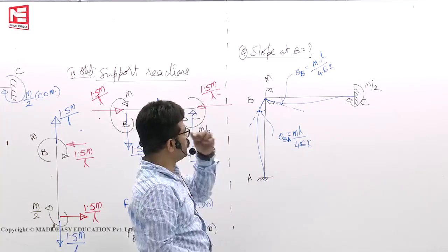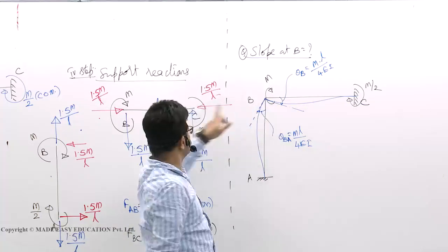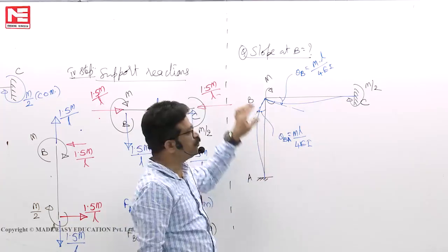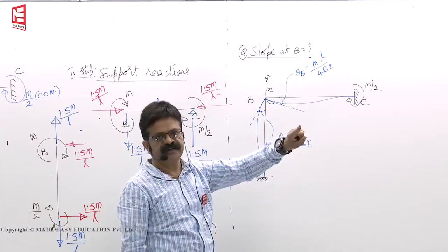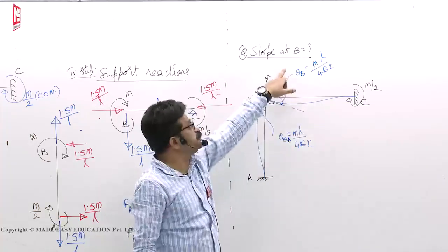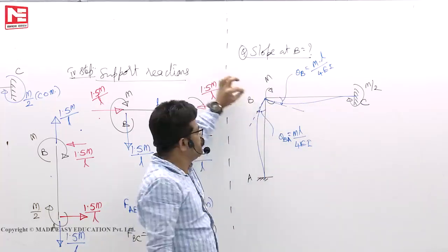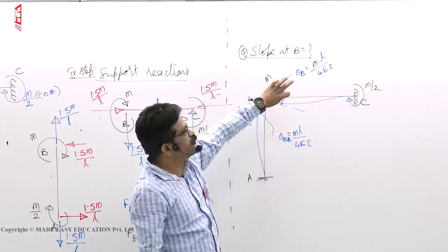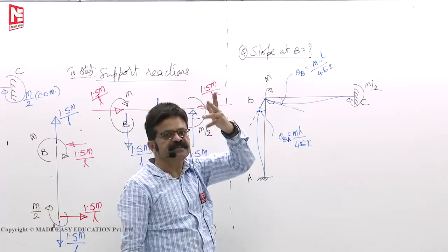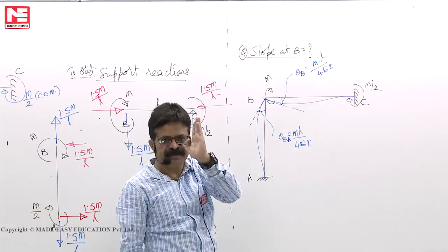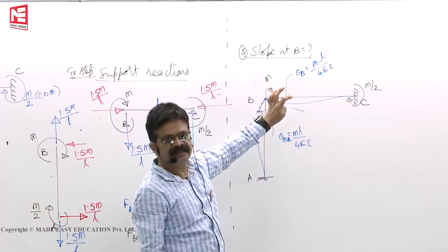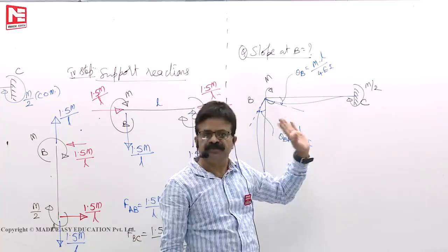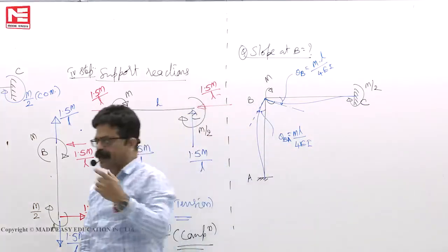So till now, what they didn't ask is this one, slope. This moment, what's the axial force, they have asked. Once axial forces and reactions are found, draw the deflection profile. That deflection profile will tell us what should be the magnitude of the slope. If this behaves now like a propped cantilever, no deflection, it is rotating. Like a prop, the only difference is in the propped cantilever, moment is 0 at the propped end. Here some moment is there. But that profile we know. When moment is acting, it is ML by 4EI. So we should be able to answer that as ML by 4EI.